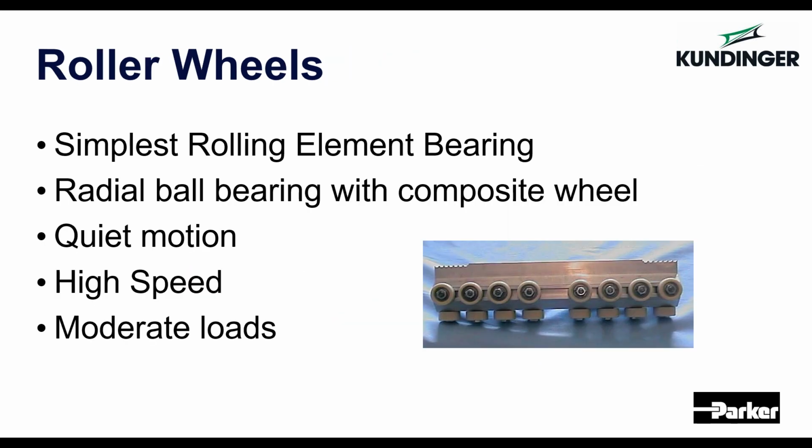So glider bushings are sort of the lowest performance and lowest cost type of guidance element we offer. Preload: any type of bearing needs some type of preload to make it work. Otherwise, you'll end up having a lot of play and the bearing really isn't doing its job. Preload is just accomplished by fitment between the element and the extrusion. There's a slight interference there where that glider bushing is going to be compressed.